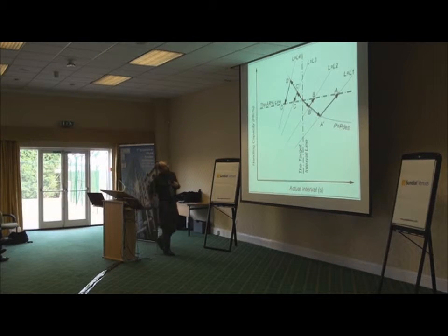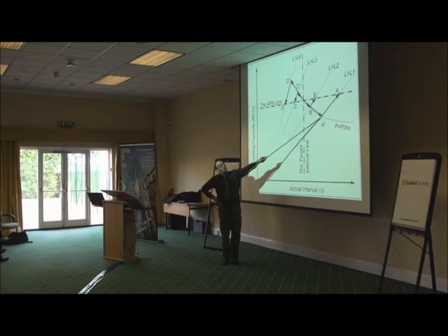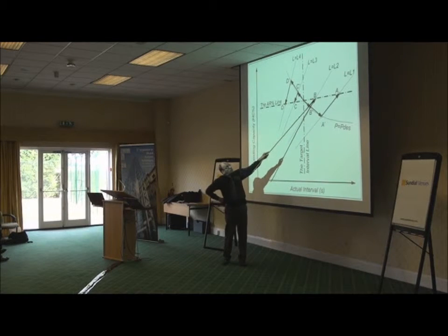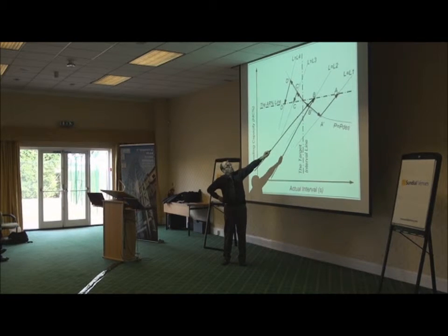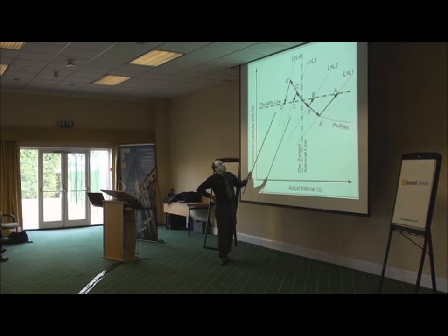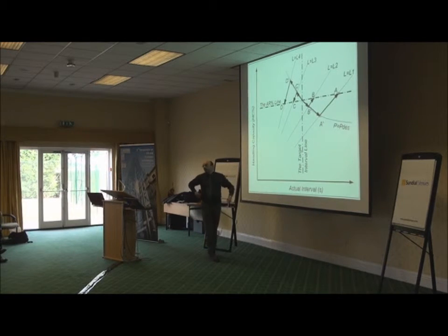And the 4 of them are shown here. So if the architect says you can only have L2 lifts or L1 lifts, which is lower than what you need, what will happen? You will move down to L2 and then move back. This is a failed design because although it meets the quantity of service, it doesn't meet the quality of service. It's to the right of the line. And the same if you had to have L1 lifts. That's a good design. That's the wasteful design because you had more elevators than what you need.